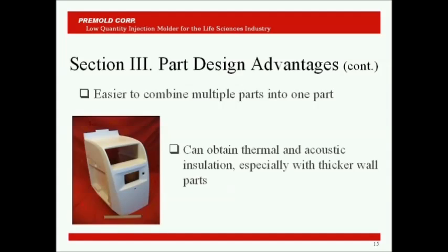Added benefits of the RIM process are thermal and acoustic insulation properties, especially when designing thicker wall parts. Also, the inherent stiffness of RIM resins means support ribs in RIM parts are usually unnecessary. This saves instrument designers and engineers space for their internal components.